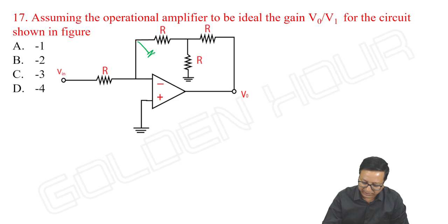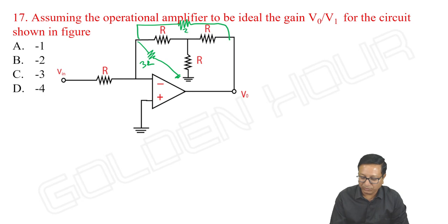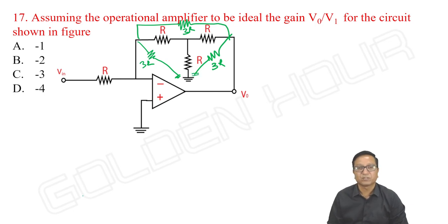So here I can write one resistor. What will be this resistor, friends? It is 3R. Again here one more resistor whose value is 3R, and one more resistor whose value is 3R. We know that, star delta conversion. Outside resistor values will be more. And further, this is similar to the previous case. So this 3R, I need not worry about this 3R and this 3R. Is it not so? Once it is converted into a pi network.